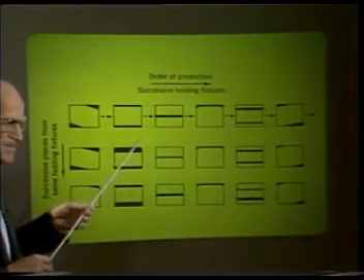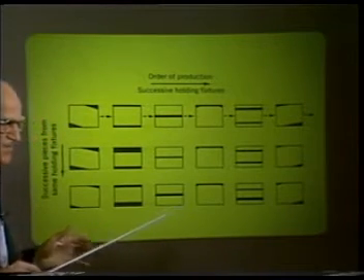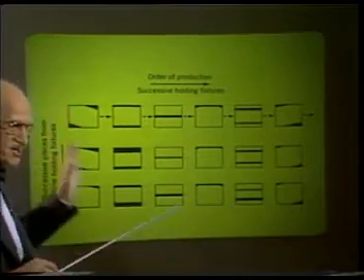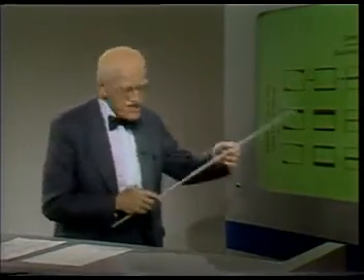A second example was the case of the polishing operation. The product exhibited many patterns of unpolish. The study team separated the product into 138 different streams, each traceable to the fixture of origin. That confirmed the theory of worn fixtures.